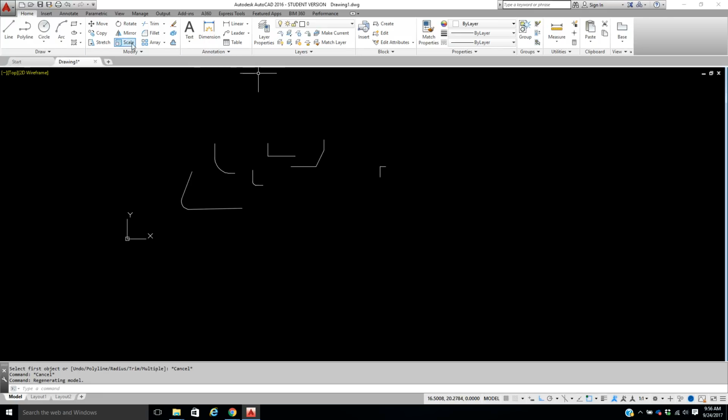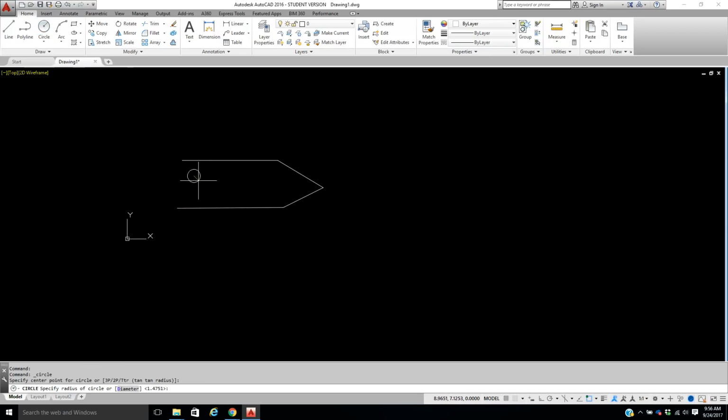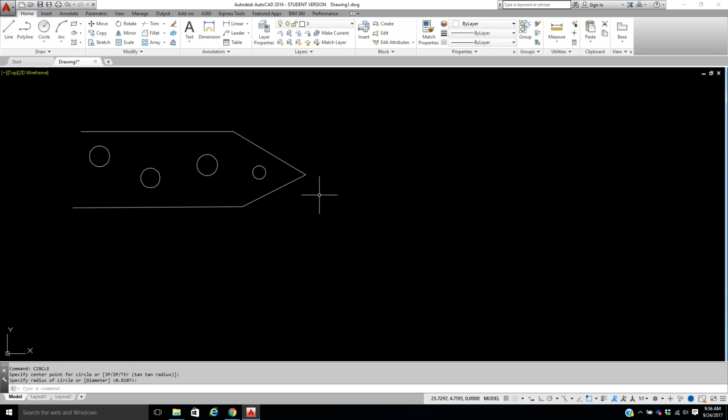let's do stretch. Stretch can be really very helpful. Let's set something up here. Okay, let's set something as basic as this kind of a shape, like so. And let's add some circles in here. Just doing this so you can see a couple of things. Stretch will be very, very helpful. Third 9 weeks when we're working on our house project, we'll be able to move the walls and doors so much easier by stretching things, so it'll help us out a lot.